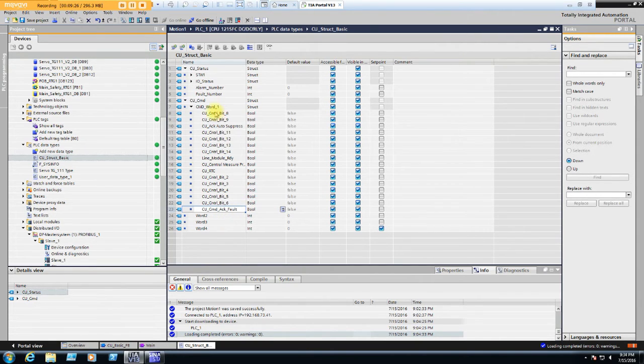You got to remember when you set up these data structures that you're doing 2 bytes in a word. High byte first. So this is the high byte. It's first. Low byte last. This is the low byte. So it's kind of non-intuitive, because when you look at it as a word, it kind of looks like it's backwards, but that's what it is. So just be aware of that as well.